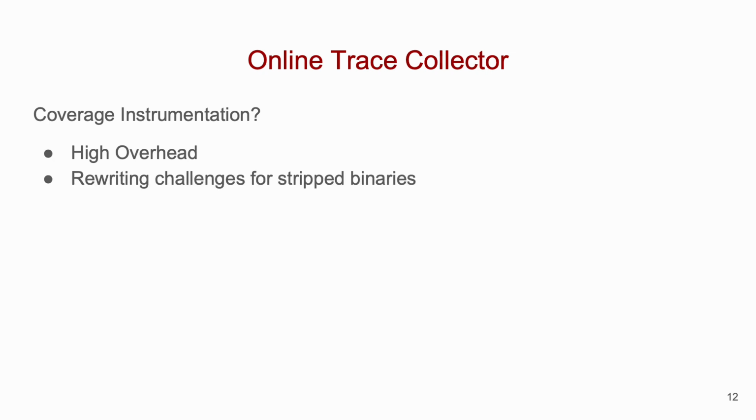So, why does mAFL not opt for coverage instrumentation like other fuzzers? First, instrumenting a binary with coverage hooks increases its size, which puts strain on the limited memory and slower operating speeds of microcontrollers. Secondly, at the time of writing this paper, no appropriate binary rewriting tools existed that reliably rewrite compiled binaries with coverage instrumentation for these microcontrollers.